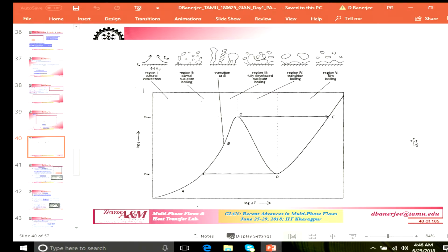But there were experiments done in the late 60s that showed that even in a stable vapor blanket mode, there is periodic contact of the liquid that hits the surface of the heater, and then by like a rocket recoil, the vapor pushes it back. So, what they did was they put some electrolyte in this solution. So, now it becomes electrically conducting, and then they put an electrode into the solution, and they put an electrode on the heater or the metal, and if there is a contact between the liquid, it should show up in an oscilloscope, and they showed that it does show up.